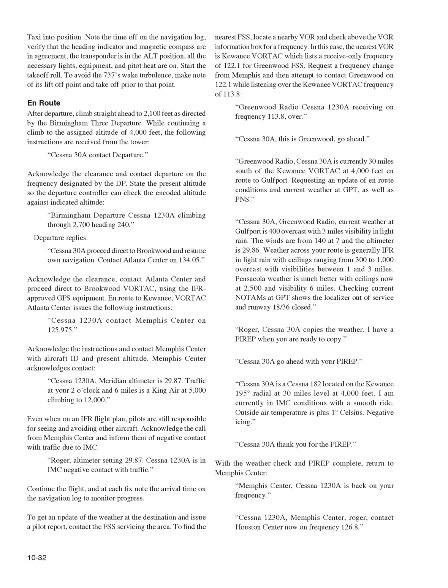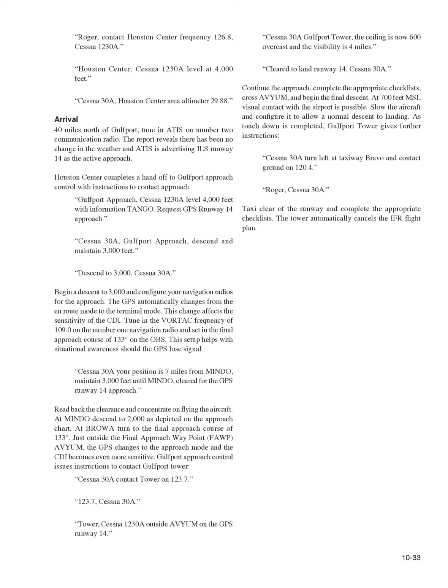With the weather check and PIREP complete, return to Memphis Center. Memphis Center, Cessna 1230A is back on your frequency. Cessna 1230A, Memphis Center, Roger, contact Houston Center now on frequency 126.8. Roger, contact Houston Center frequency 126.8, Cessna 1230A. Houston Center, Cessna 1230A level at 4,000 feet. Cessna 30A, Houston Center area altimeter 29.88.